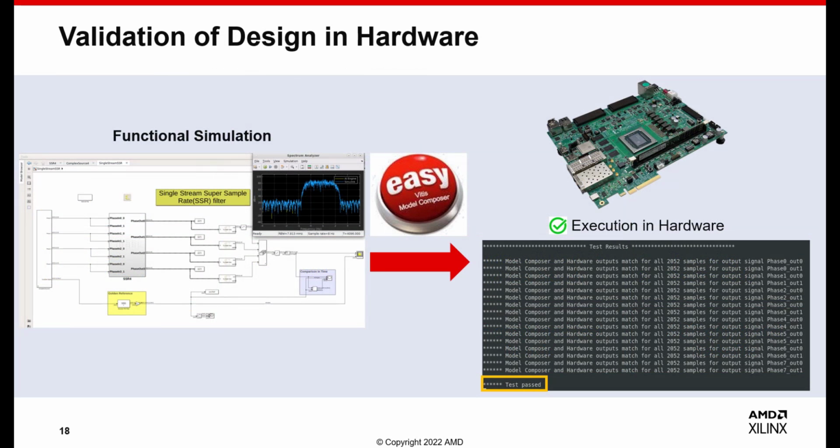You can also easily validate your design in hardware. Generate the data movers, PS code, and configuration file. Generate the makefiles needed to build a design for hardware. Move the design into hardware with a click of a button.